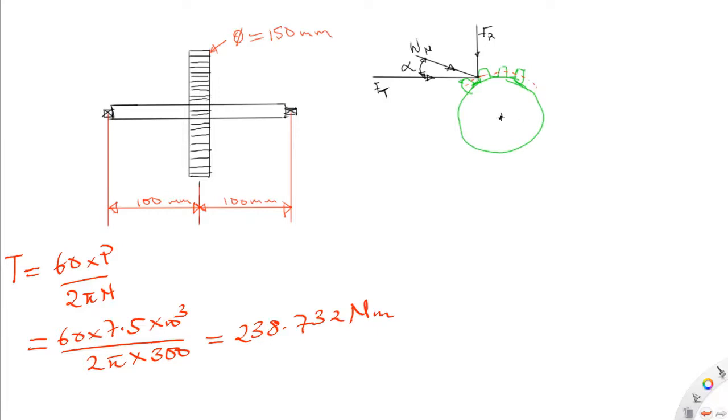So if we take the center of the gear to be this point, this load here is the resultant of the radial load and the tangential load, and that will be what will bring the actual bending. Actually, we'll have bending from the radial load Fr, and we also have bending from the Ft, which is the tangential load.